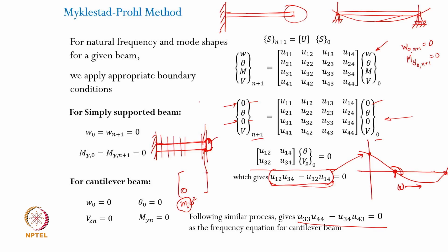If you can formulate and understand the geometry here properly, and this mass is distributed reasonably over a longer length, then you can also assume this to be a separate segment. But then that segment's flexural properties will have to be properly evaluated and used as the last segment. Its own mass distribution can then be lumped at the end, and that is how you need to make use of these.